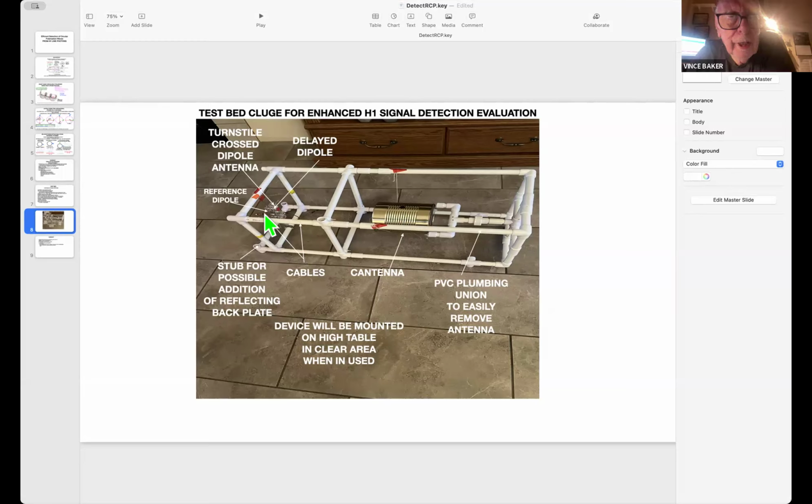It generates a signal polarized this way. You shove it forward, and then you delay it. And when you get here, they're at 90 degrees apart. And now you have a 90-degree thing rotating this way. I could have probably done a better chart for that. But that's how the turnstile works. It's called the turnstile.